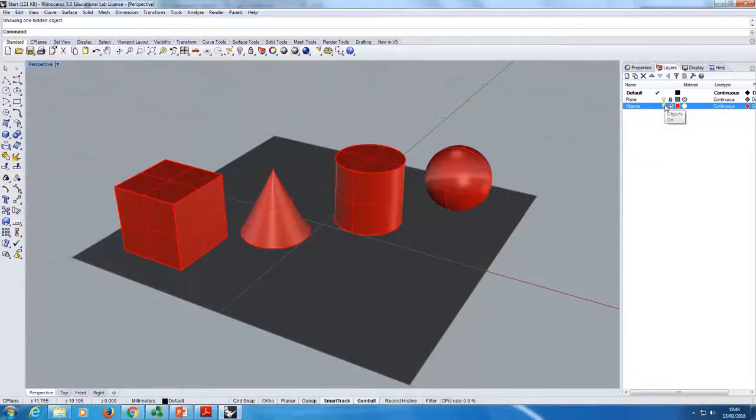When you work on complicated projects, I would strongly recommend using layers. They will make your life easier. You can activate, deactivate them. For example, you would draw your construction lines in one layer, then you draw on top of them, and then you can hide your construction lines so it looks very neat and you don't get too messy, hopefully.